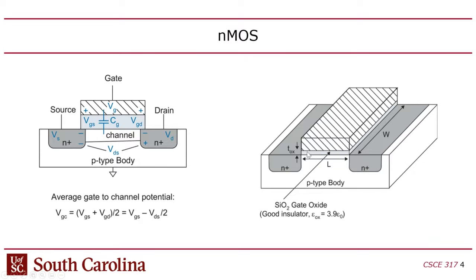I think that the oxide thickness tends to shrink a little bit too with more advanced fabrication processes as well. But generally, when you think of a new process, it has to do with focusing on the length and width and scaling those down. Both the PMOS and the nMOS are basically capacitors, where the gate is one plate of the capacitor and the substrate is the other plate.